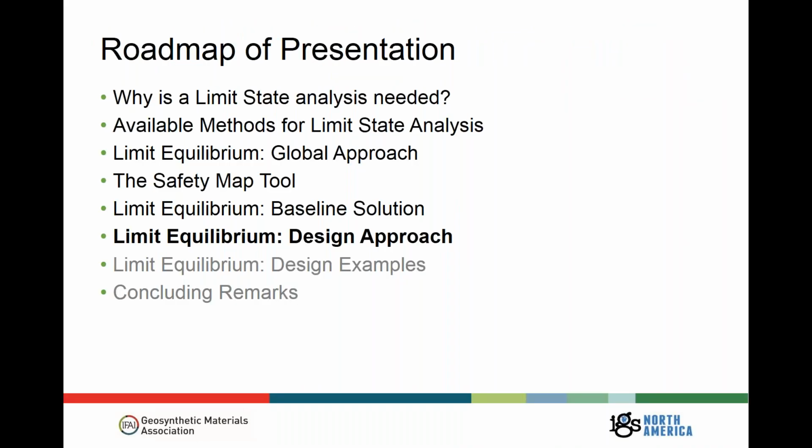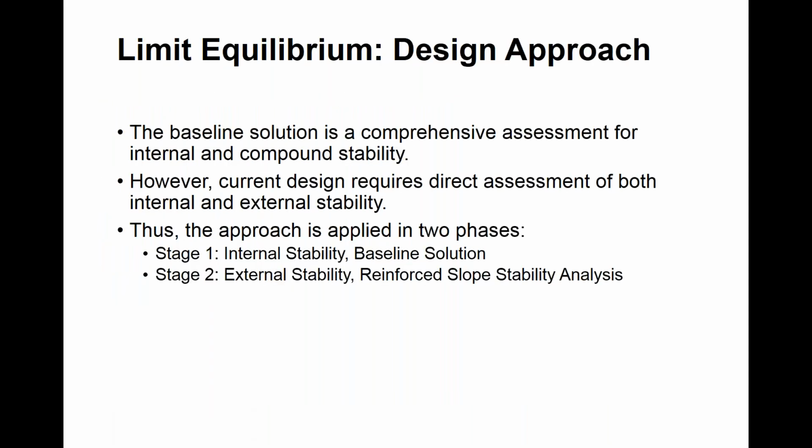Let's talk about application in design, because you're all practitioners and you're out there doing the real stuff. So let's talk about how this might be applied in design. The baseline solution, which we discussed, with safety factor 1 everywhere, getting tensions in the reinforcements, is a comprehensive assessment for both internal and compound stability.